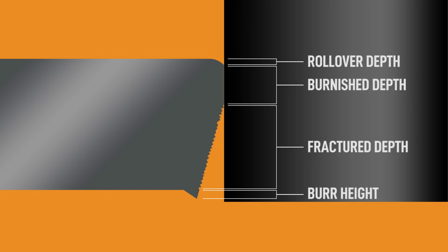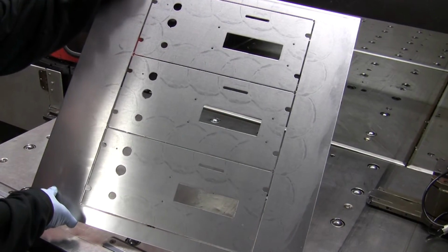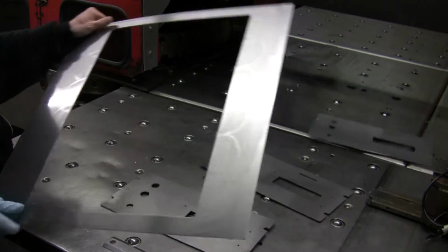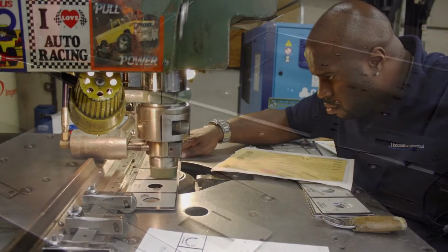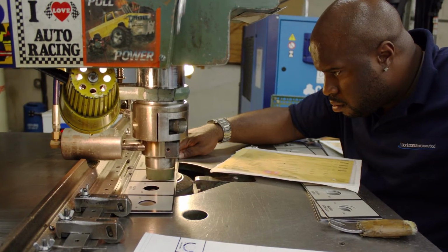As the punch makes its exit through the material, it again forces the material downward, leaving a small piece of material remaining attached to the workpiece. This is called a burr. These are important considerations for jobs with high finish specifications because these types of blemishes require additional finishing processes, which will increase time to finish and costs.